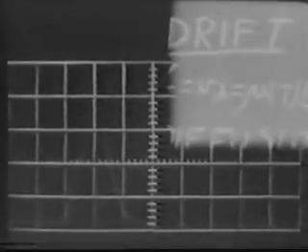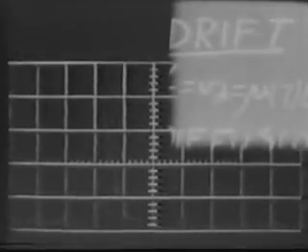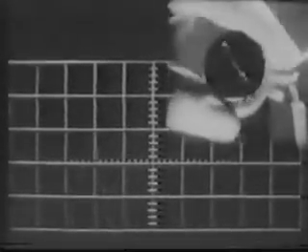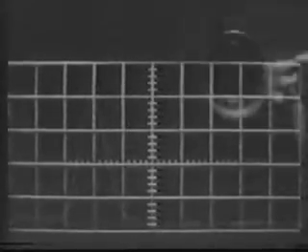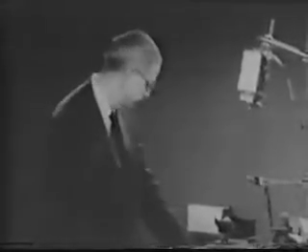According to the mobility equation, the velocity should decrease when the electric field is decreased. When we decrease the field with a potentiometer, the delay time increases as expected and decreases when we raise the field again. Now we are ready to measure the electric field in the bar. I'll connect the voltmeter to the two phosphor bronze points.